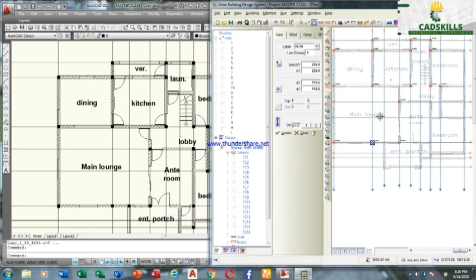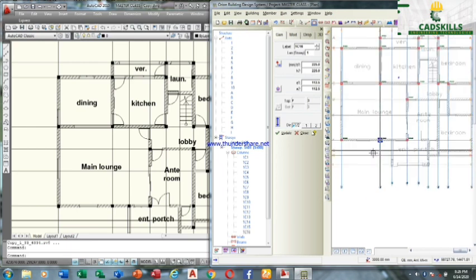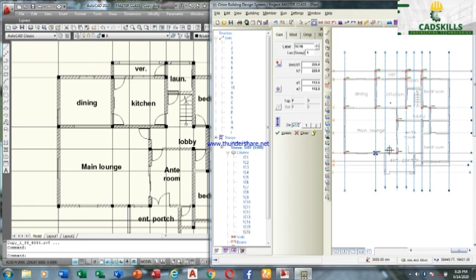There are places we're introducing beams, so I want to put a column here to take care of this beam that will be coming here on top. Please take note. Now this span between here and here, this column is enough. Alright, and I'm going to put a column here also, so this beam can carry this. Of course this doesn't have much load, so it's not a must that your columns must be at the junction. Take note, you must understand the general arrangement and the reason why it is so.